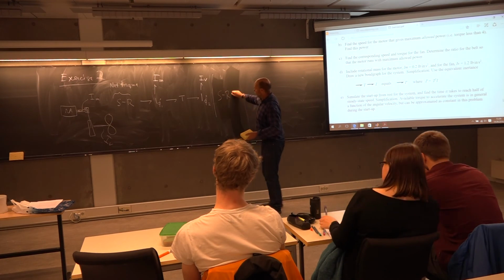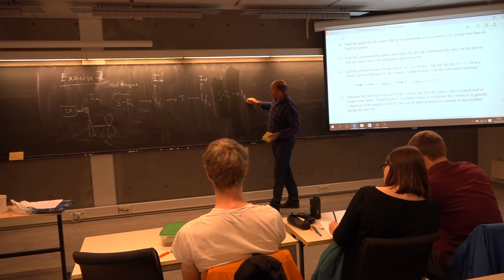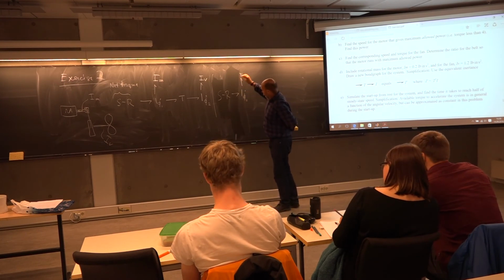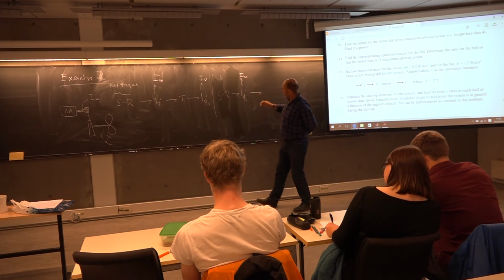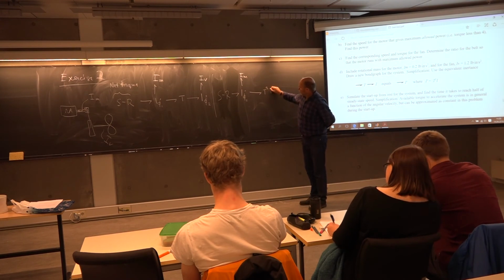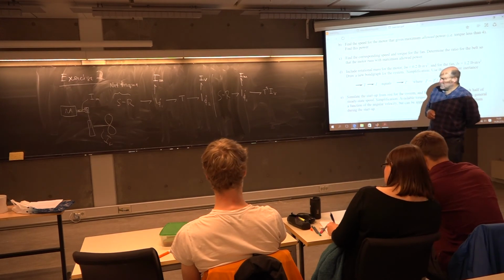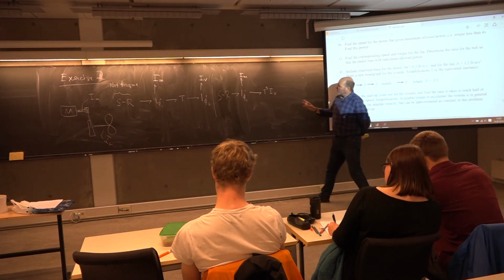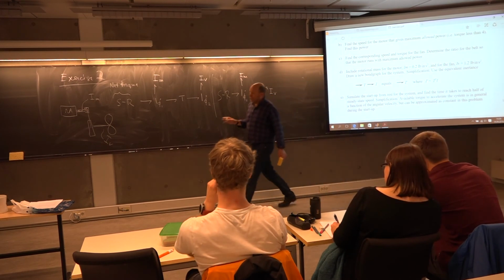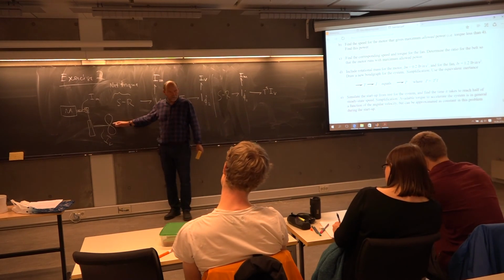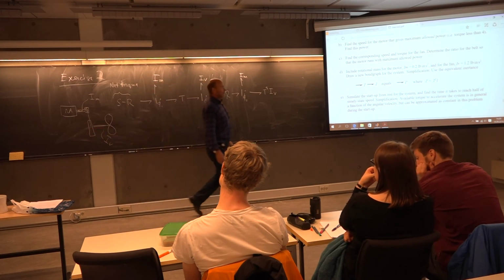S minus R hitting the first one junction, phi1 dot, Im, and this one now will be T squared Iv. So it's a little strange way to think, but this is sort of the rotational mass from the fan that the motor feels after this gear has been coupled in.